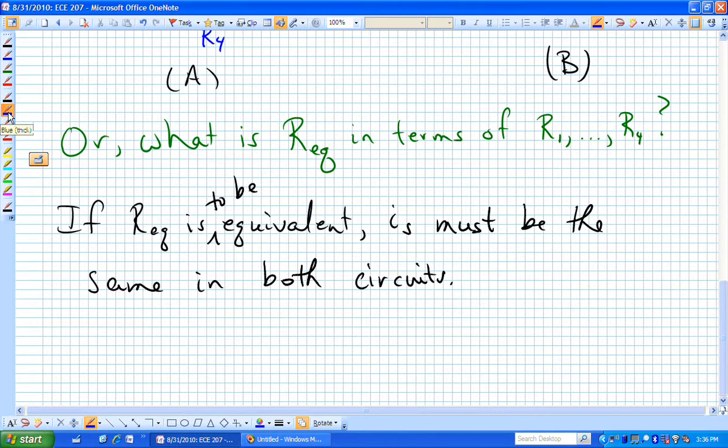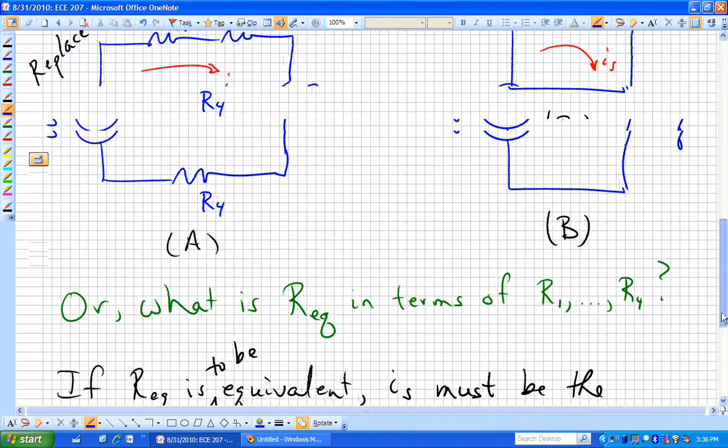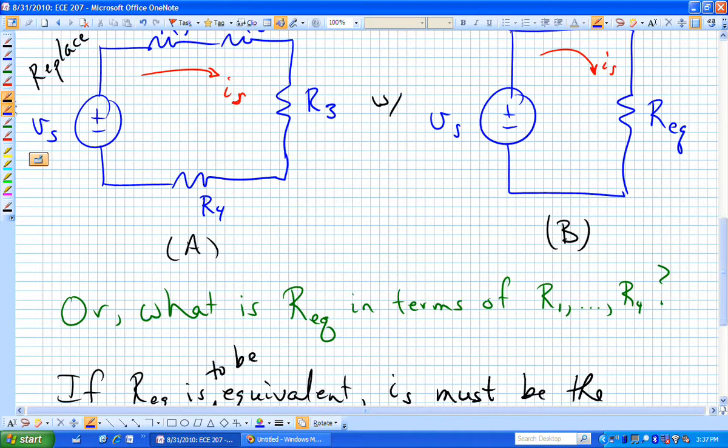If that's the case, let's go ahead and analyze both of those circuits. Suppose we do a KVL in circuit A. And if you're remembering what we had done last week, we might define that as a single mesh, where that dashed line is a mesh that we are going to travel as we go through those different elements and sum up those elements. Once we return to the place that we started, that sum should equal 0.